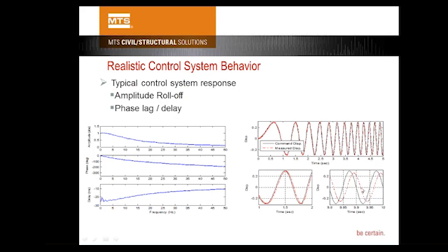This delay could be 10 milliseconds, could be 30 milliseconds, but it is always there. In a regular test this delay doesn't matter, who cares about 30 milliseconds? But in hybrid simulation it is a systematic delay, always there, and the numerical model doesn't care about that; it gives us a command and then reads the feedback.